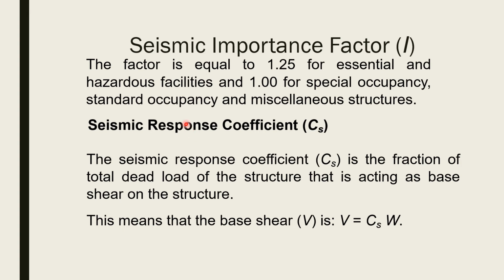Seismic response coefficient. The seismic response coefficient is the fraction of the total dead load of the structure that is acting as a base shear on the structure. Let me explain. You are designing a building, then definitely that building has some weight. So what is the seismic response coefficient?